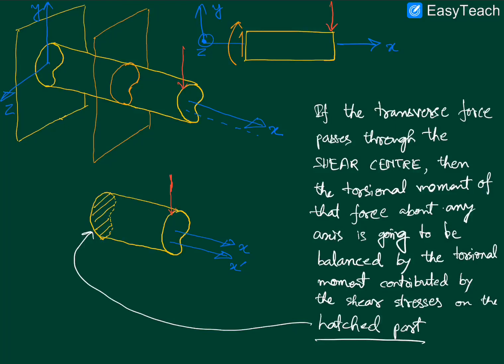And please note that of course this torsional moment contributed by the shear stresses also has to be computed about the very same axis. Okay, so this is the entire physical understanding behind the shear center and the whole story associated with the possibility of twisting under the action of transverse forces.